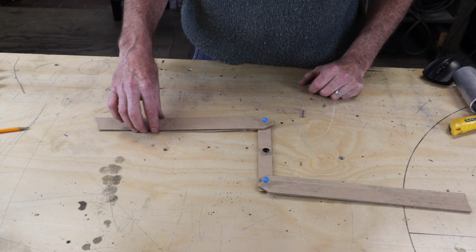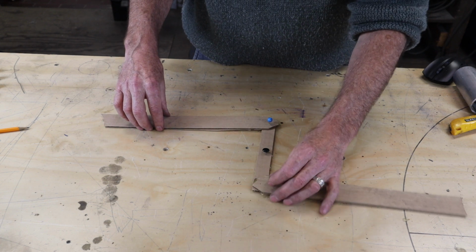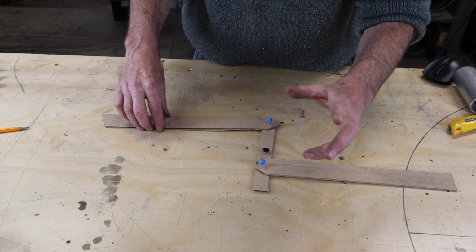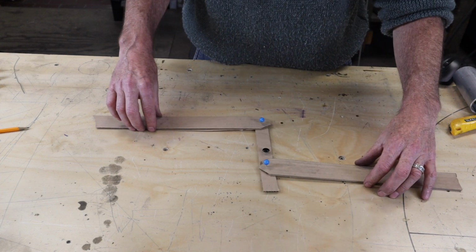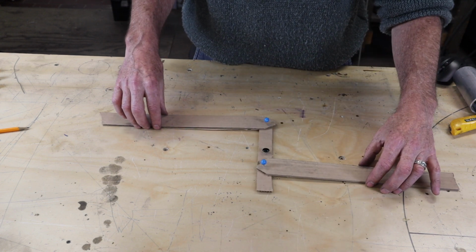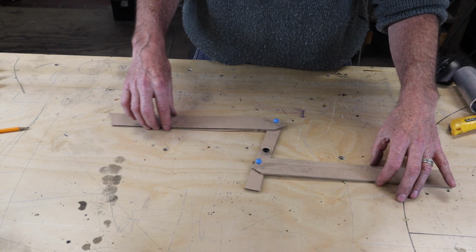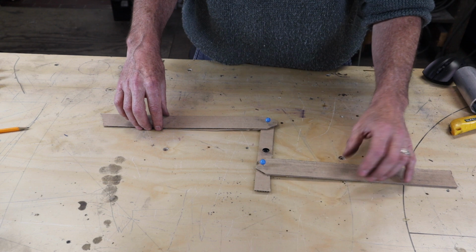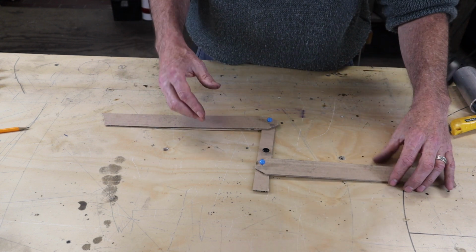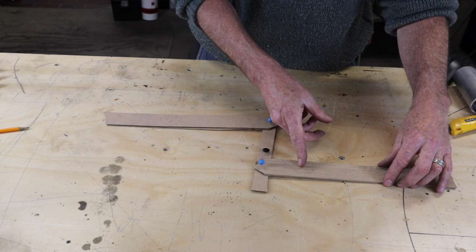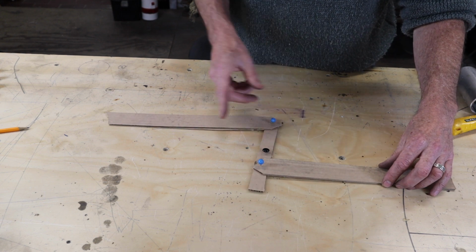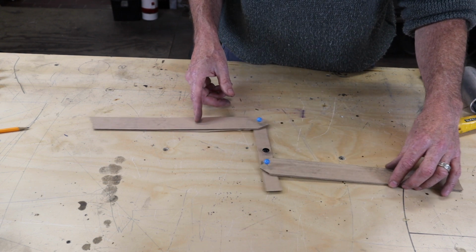And you can compound this. You can change the relationship between. Effectively, we're changing the gearing now. So now this bottom one moves a lot, and the top one, this being the top, moves only a little bit, but with more force, probably with about twice as much force. And again, you can reverse this so that your driven one is moving a little bit, your driving one is moving a little bit, and the driven one is moving a lot.